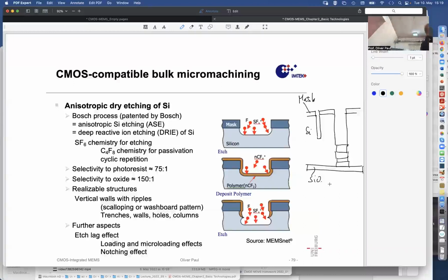Unfortunately, it does not just stop, but it continues by etching sideways, because this oxide gets charged, and then etch species are redirected, and the vertical directionality is also a lateral directionality then, and then you don't end up nicely with clean walls. And apart from that, those walls are not flat anyway.